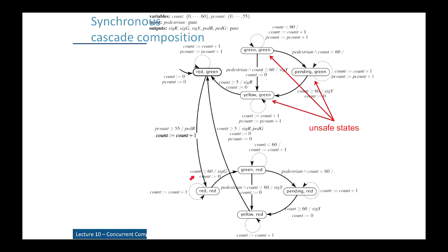until the count hits 60. Now, it so happens that when you're in this default state, you reset both the counters. They're both added to 1. When P count gets above 55, we go to here, and count is still increasing. When it gets above 60, we go to the opposite, green, red. In other words, it's like a 5-second overlap where both lights are red. It's a bit of a protection mechanism, right? Stop red light runners and all that sort of thing. So there's a 5 reaction overlap here, and we migrate to then the green-red case.